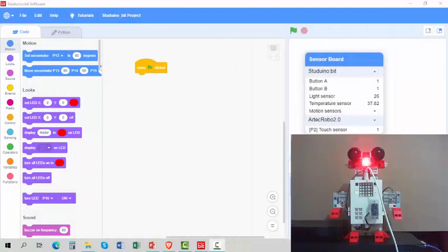Okay, fantastic. So let's work with the servos at the moment. We've got a servo that will control the head from the center position to the left and right position. The problem for us with servos is it's got a limited range, and we need to figure out what the range is at the moment. Range is a big deal for us, and obviously you will see on the little Khodibot the cables are not that long, so we need to limit how far we want it to move.